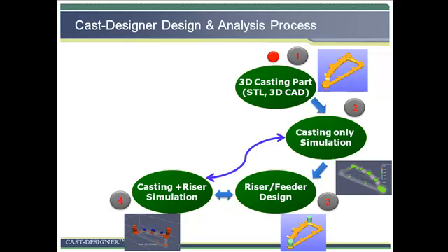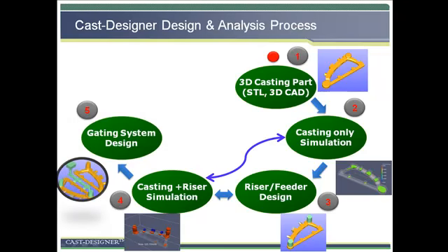Then, another simulation with part and riser only will be performed, to check the feeding distance, and if the liquid spot could be compensated well in the solidification process. Now, we will design the gating system.